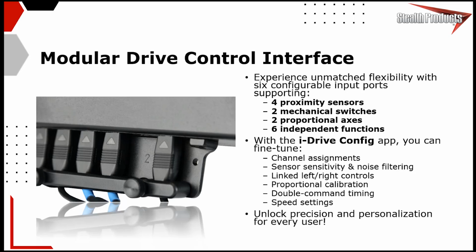We can filter out electrical signal noise for a lot more precision on our sensor activations. We can do double tap timings. We can set maximum percentage of the programmed wheelchair speed. So all of that within the iDrive gives us a pretty unmatched level of precision, control, and more importantly, personalization out of our drive control.